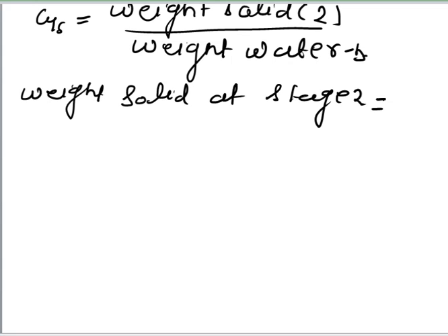So look, all those experiments are related in a series manner. The parameters you have to determine, all those experiments are related anyhow. Okay, so this is the concept which you have to understand: before determining the specific gravity using the pycnometer method, I have to conduct oven drying, then conduct the pycnometer again to determine the water content.